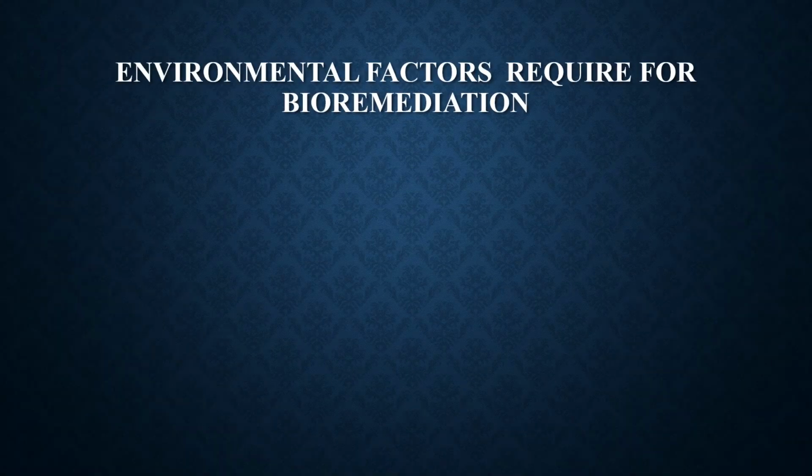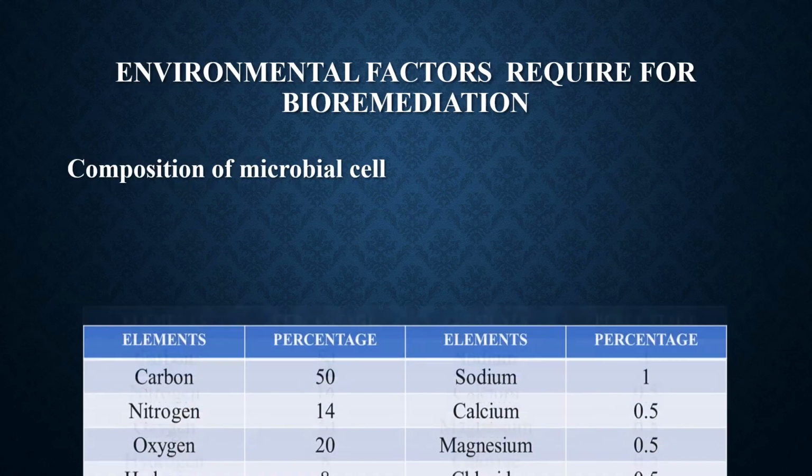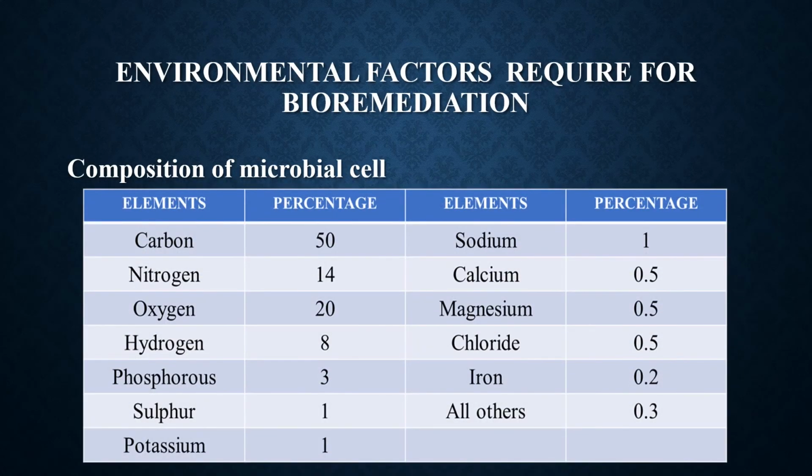Environmental factors required for bioremediation. Composition of microbial cell. Nutrients are the basic building blocks of life and allow microbes to create the necessary enzymes to break down the contaminants. All microorganisms need nitrogen, phosphorus, and carbon to secrete the essential enzymes to break down the contaminants.